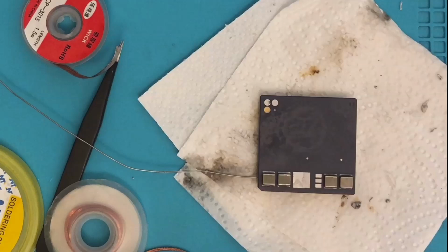I don't think this is a good idea. You see, there are two problems with the diodes. First of all, for sure they're not too stable with big fluctuations in current. But I think the most important problem is the stability with temperature. So basically when you boot up and 10 minutes later you will get a totally different voltage, maybe by 200 millivolts apart. The other thing is the amount of steps you get.